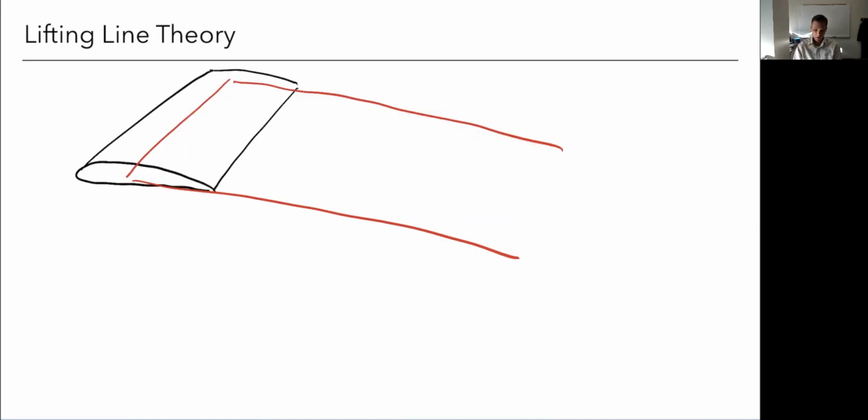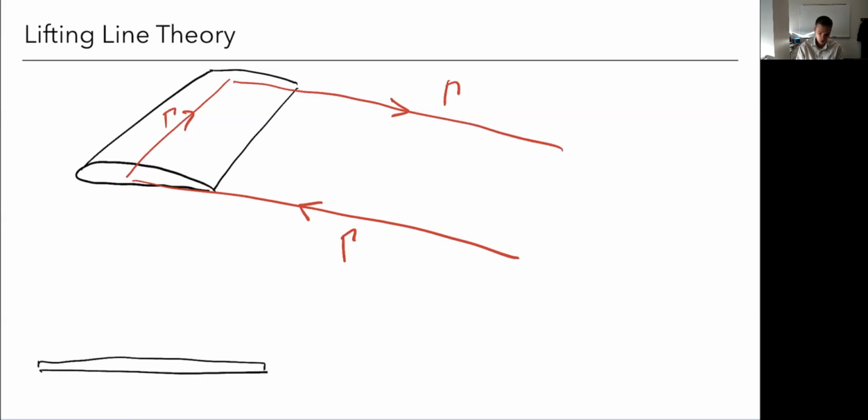We also saw that this appears to match some physical experiments, but is an insufficient model in matching reality. For example, from the theorems, we know that the circulation gamma must be constant everywhere along that vortex, right? And it's in this direction as shown here, inducing a downwash in between. If I looked at, say, a back view of the wing, because gamma here is constant all the way across the wing, that would mean that the lift distribution, the circulation distribution, would be a constant line here. Pretend I drew a straight line there.